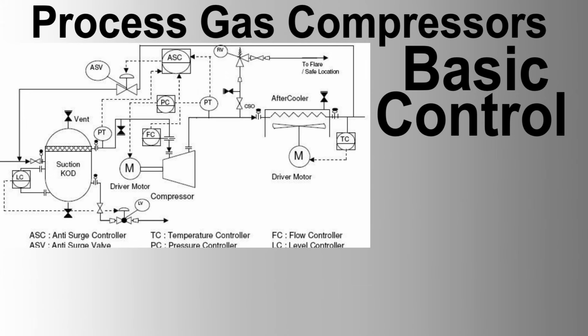Variable frequency drive, VFD, adjusts the compressor motor speed to maintain the desired suction pressure. Operation. 1. Pressure measurement. The PT located at the compressor suction line measures the suction pressure and sends the signal to the controller. 2. Signal processing.